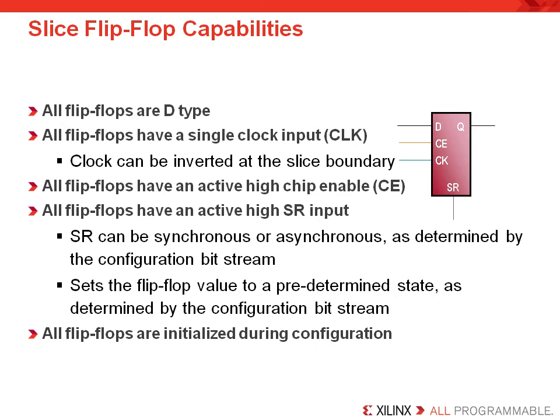All flip-flops have an active high set reset input as well. The set reset can be synchronous or asynchronous on the local flip-flop, so that is programmed locally, and this is determined by the configuration bitstream that is finished by the implementation tools. You also have the ability to set the flip-flop value to a predetermined state as determined by the configuration bitstream as well, and this is chosen by default based on your HDL coding style. All flip-flops are also initialized during the configuration process by default.